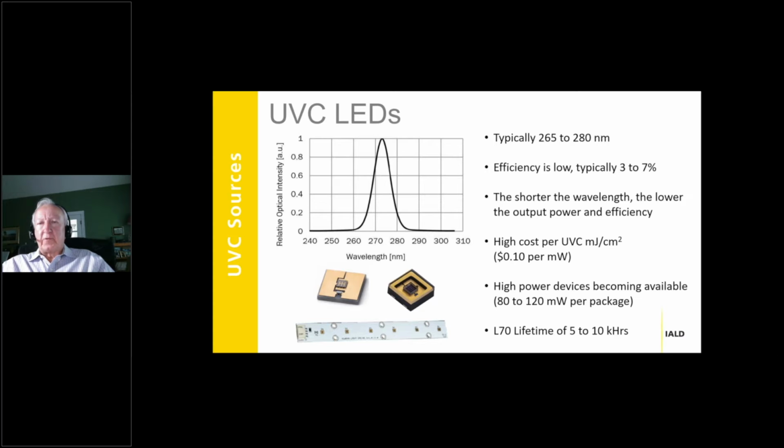Finally, it's going to be important to remember that UVC energy damages materials, and the same is true for the materials that make up the LED device in the package, which is one of the reasons why the reliability of UVC LEDs is problematic. Those high energy photons coming out of UVC LEDs damage materials in the LED material itself and in the packaging material, and it's going to be a consistent problem for UVC LEDs.